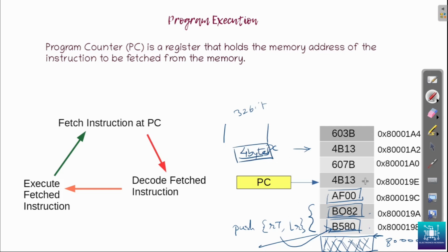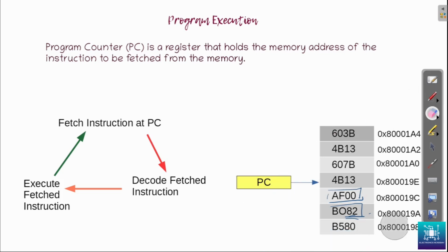Even though the instructions are 16 bits, it jumps at 32-bit boundaries and then grabs the instructions. So if there is a 32-bit instruction, then if the PC jumps 2 bytes, it will be only one instruction that is coming in. But if it is 16-bit instructions, when the PC jumps 4 bytes, it gets 2 instructions. This is how it operates.